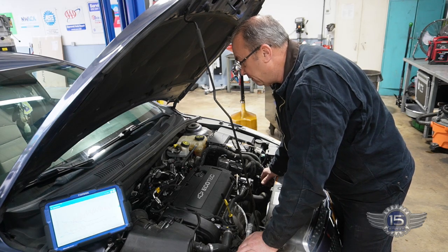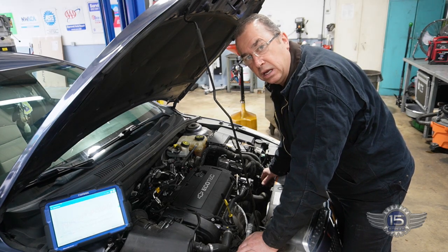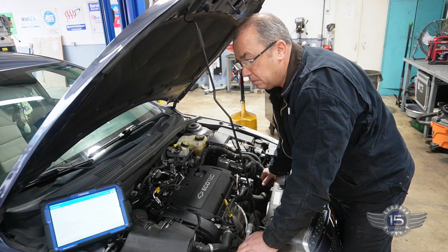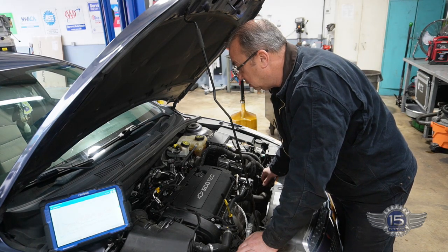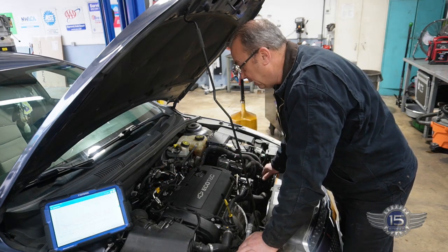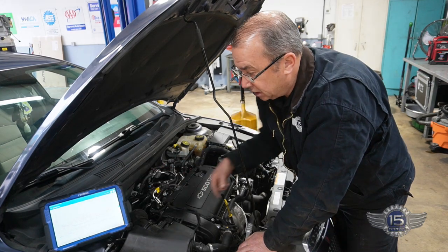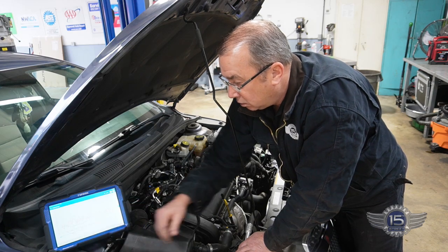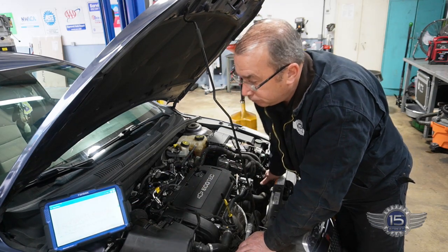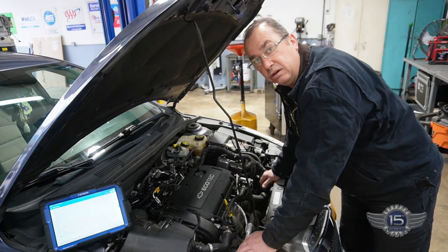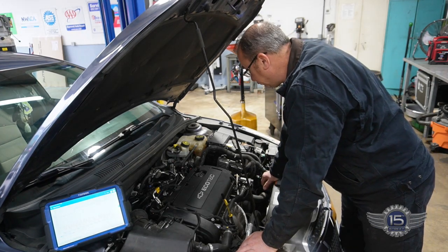So we need to go after that purge valve and see what is happening. I was thinking maybe our problem was a vacuum leak, but all I've done is remove the electrical connector on the purge valve, and you can see we're at 5%, -3. So we've got a combined 5, 6, 7 fuel trim.